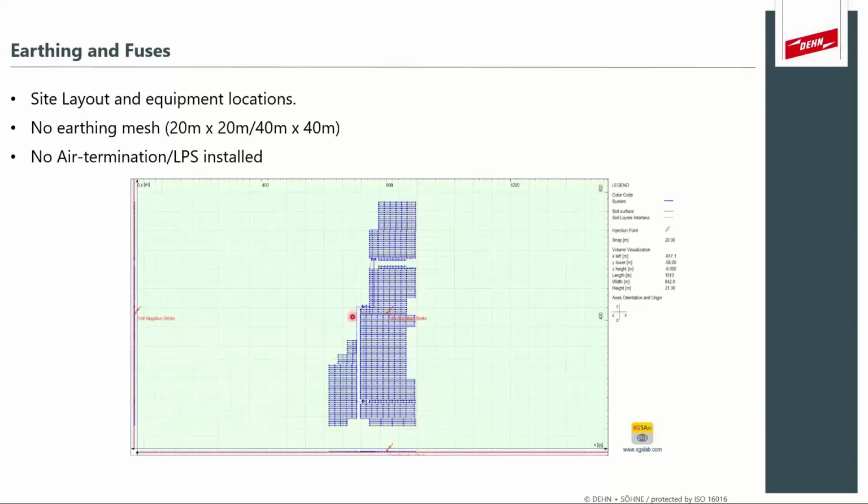It's made up of 3 different blocks in this case. Each block has its own inverters installed. Okay? And what you can see is there's no meshed grounding system in this case, but also they have an islanded system. So this top portion and this left portion is actually not connected via the grounding system to this main central portion. Okay, so the current distribution, we assume, would heavily distribute through the electrical network to make its way to the other parts of the islanded grounding system.